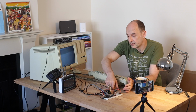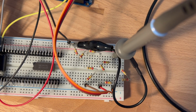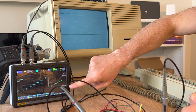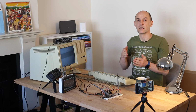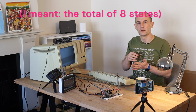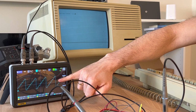So basically, I upload the code, I run the code in Arduino and connect the other probe to the end of the ladder, and there it is, beautiful. What we see here is 8 levels of volume nicely represented. The code in the Arduino goes through all possible states of the 3 bits, which is a total of 8 states, from 000 to 111, and it repeats the pattern every several milliseconds, I think.